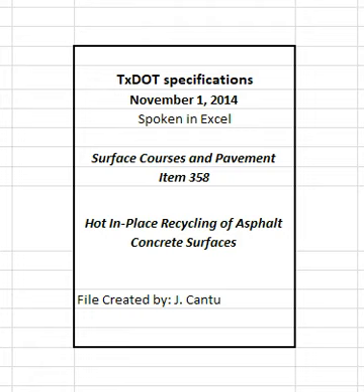6.3.1 In-place air voids. The engineer will measure in-place air voids in accordance with Tex-207-F and Tex-227-F. Before drying to a constant weight, cores may be pre-dried using a CoreLok or similar vacuum device to remove excess moisture. The engineer will use the corresponding theoretical maximum specific gravity to determine the air void content of each core. The engineer will use the average air void content of the two cores to determine the in-place air voids at the selected location. The engineer will use the vacuum method to seal the core if required by Tex-207-F.